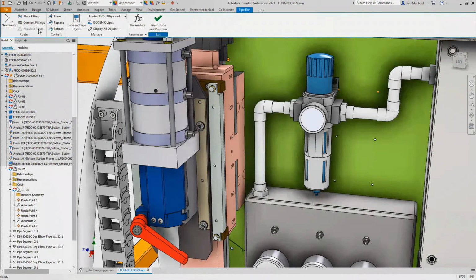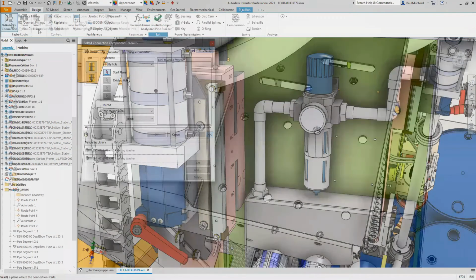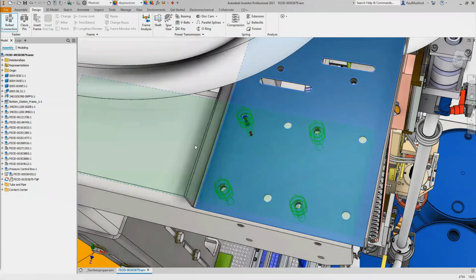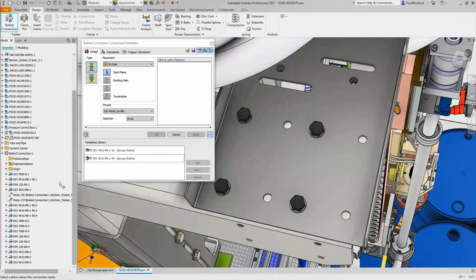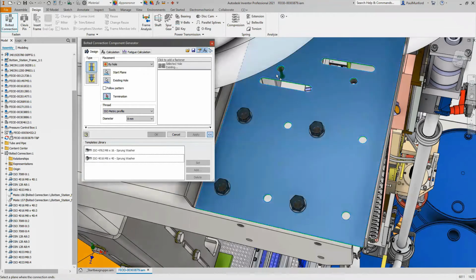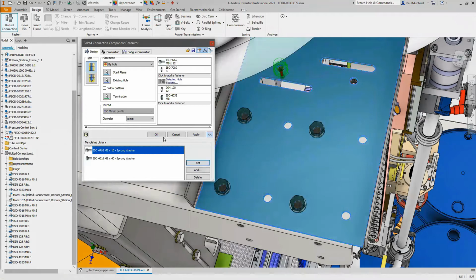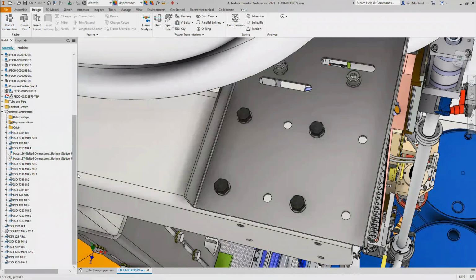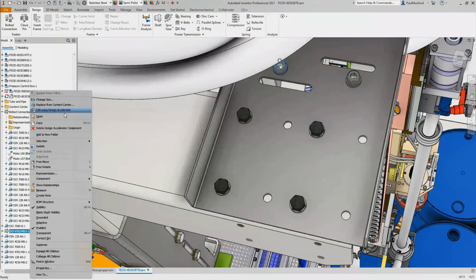In this example, notice the new option to disable the subassembly structure. With this option active, no folder or subassembly will be created on disk. The individual components will be inserted directly into your assembly. This gives you more options for structuring your assembly and organizing your data to best suit your needs. You'll notice the difference immediately when you look at the assembly structure in the browser.